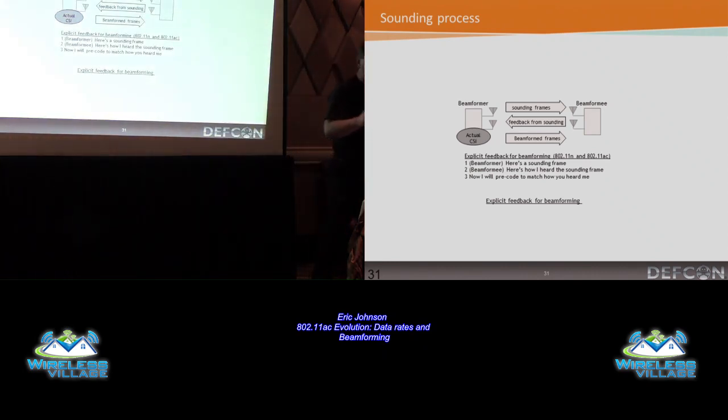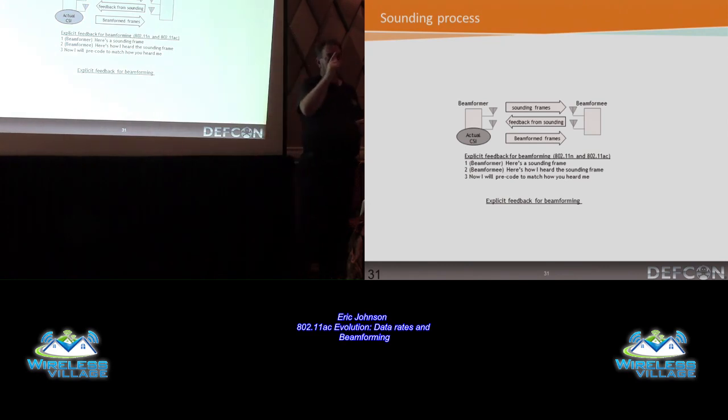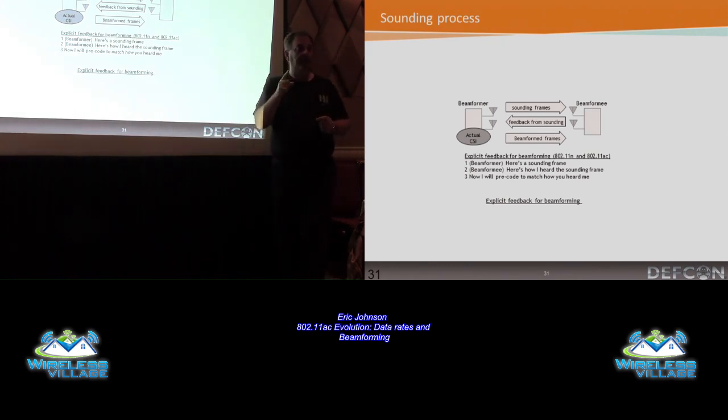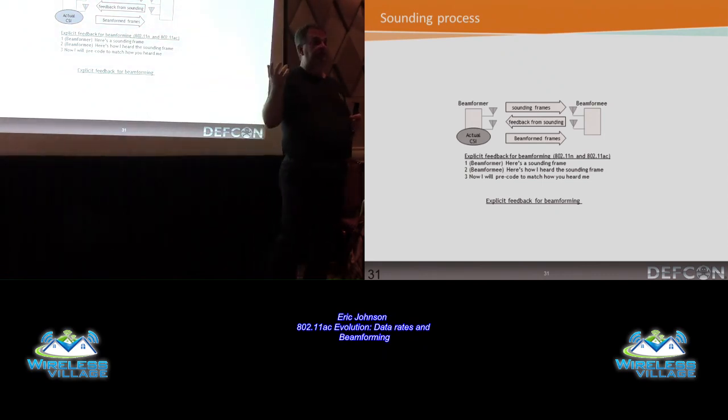One of the things that's different, and so beamforming is actually not a great name, because what it's actually doing, so if you think about some of the analog beamforming solutions you see, this is basically where they're either physically turning an antenna or changing some pin diode switches so they're shooting energy out in different directions. That actually is only doing one thing. It's trying to maximize the signal strength at the client. The problem is that works great if all you're dealing with is a single stream.